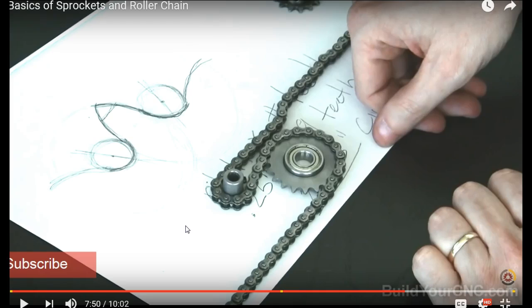So we have tensioners like he's talking about. These idler wheels, it's tensioners. Like in a 10 speed or 15 speed, if you got a bicycle, especially changing gears, the chains have got to be so many different lengths that it's got that tensioner back there or that idler wheel. It's got several functions. It does what? It allows us to change the gear ratio, or the sprocket ratio is probably more correct, to get different speeds.